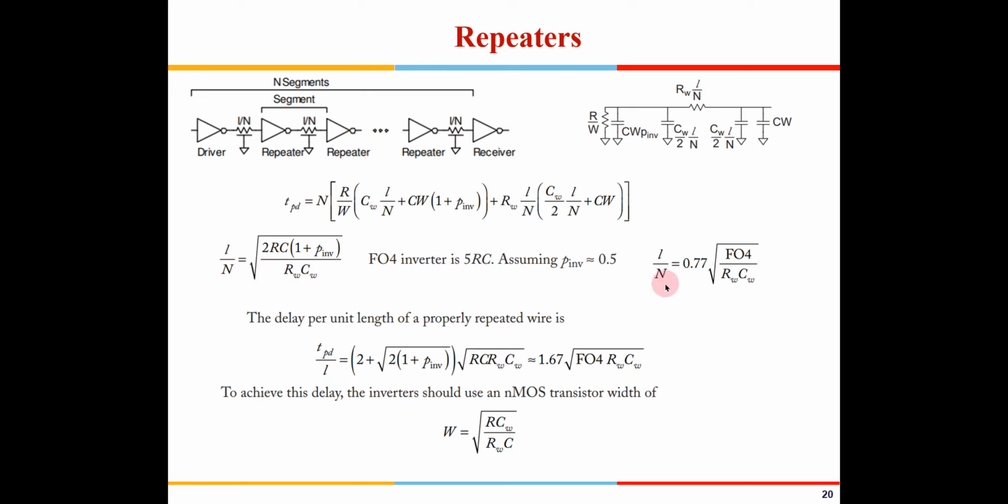In case you are going for a design, the size of these inverters also has a formula given, based on the values of the wire resistance, wire capacitance and the total length. So such kind of mathematical analysis is also available, and you need to keep that in mind.